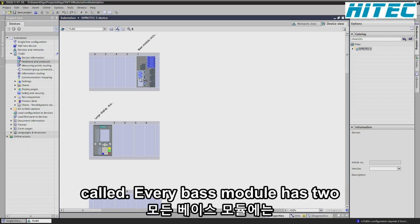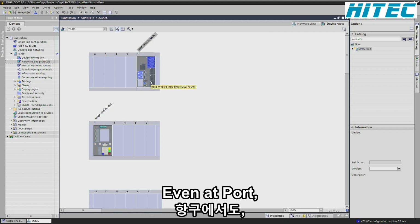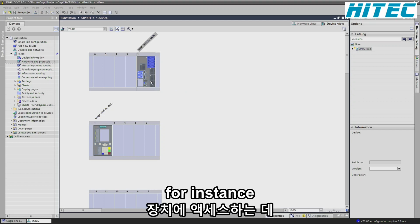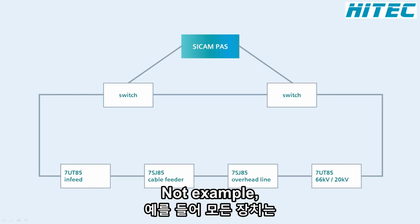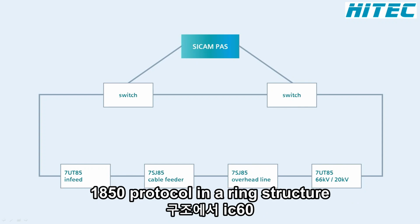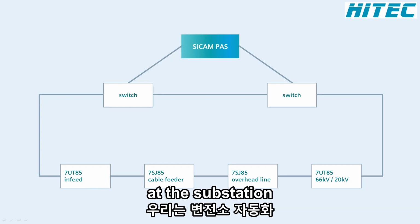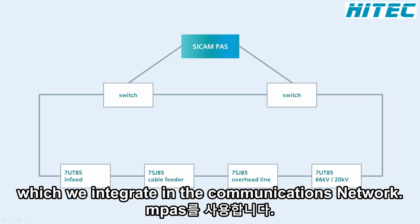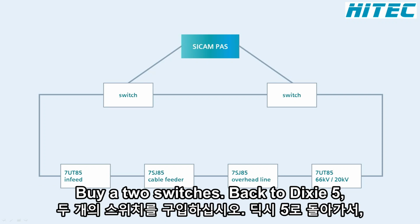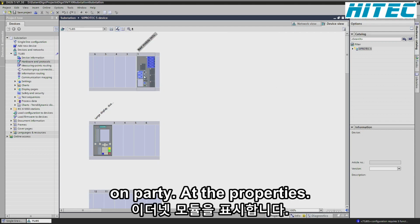Every base module has 2 slots for possible plug-in modules and comes along already equipped with one Ethernet port, the port J, which you can use, for instance, to access the device with Digsi-5. In our example, all devices should communicate via IEC 61850 protocol in a ring structure using RSTP, as we see it here on this graphic. As a substation automation system, we use a SICAM PAS, which we integrate in the communications network via 2 switches. Back in Digsi-5, we mark the plug-in Ethernet module on port E.